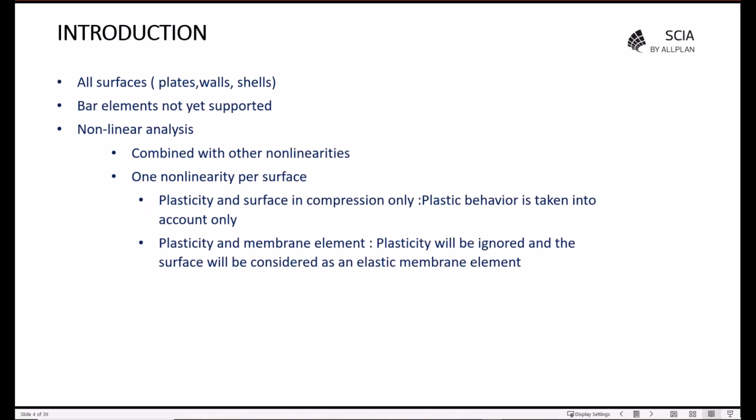The plasticity criteria is applied to all types of surfaces: plates, walls, and shells. What we should note is that if we have a 1D element, a message will appear when we run the calculation that the plasticity will be neglected for these 1D elements. The plasticity is a nonlinearity, so we should run a nonlinear calculation to take it into consideration.